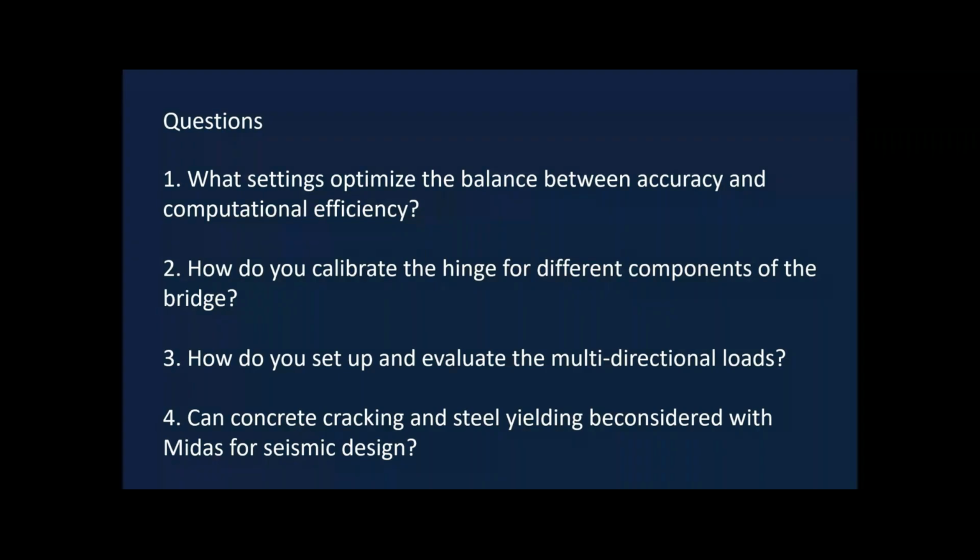So the choice of the plastic hinge model is very large. Even in Midas, there are different types of plastic hinges available. It could be Takeda, it could be multilinear, bilinear, or trilinear, or FEMA type of plastic hinge. But the choice of the plastic hinge depends directly upon the engineer.